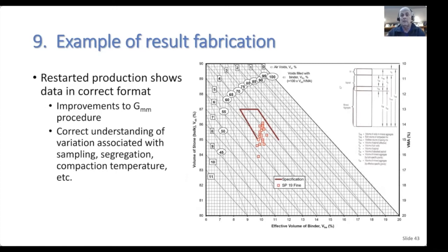And, you know, one of the issues I said to both the contractor and the consultant, that, yeah, every now and then you're going to get a result that fails the specification. Doesn't necessarily mean that the material is bad. It might be that something's gone wrong with the laboratory technique or something else. So what this does is it creates a warning or something that you need to go and look at. But you have to start off with having the correct premise and the understanding of how this material behaves. And you can't do this if you don't look at the volumetrics in the true manner, and if you don't look at quality control trend charts for really assessing material performance.